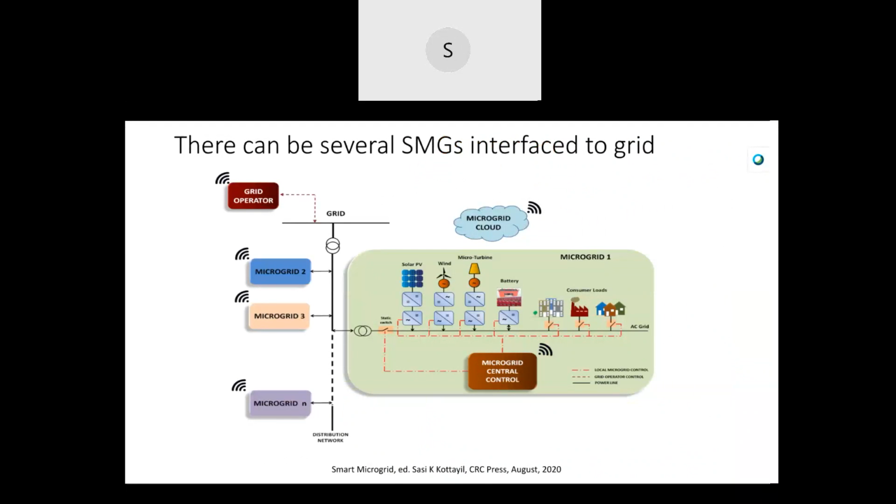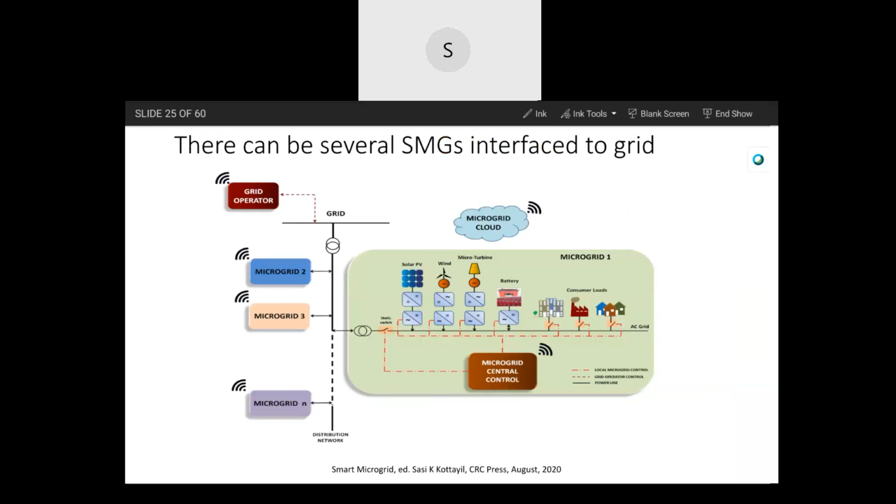See, here one microgrid is shown in detail, that has solar, wind, even gas turbines, micro turbines, battery storage, and different types of load: commercial, industrial, and residential. And it has 2 modes of operation. It is hybrid in mode of operation, either grid connected or islanding. If it is islanding, it will be controlled by the EMS separately.